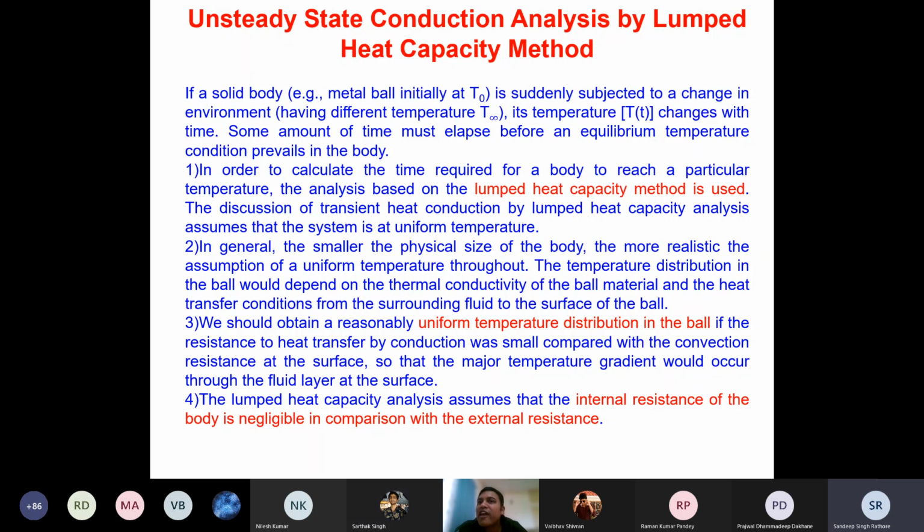So we will not be able to say in a generalized way, because in forced convection, you can add turbulence and you can have higher heat transfer there, right? So a generalized thing we will not be able to say, but for thermal conductivity, you can say with conviction that the thermal conductivity of a solid is going to be much higher compared to the thermal conductivity of a fluid. That you can say.